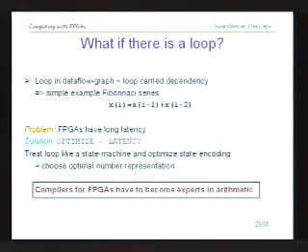The way to deal with that is, for example, to choose a number representation where this add can be done very quickly. So you could transform x and y into a redundant representation and use redundant arithmetic to speed up the actual computation. With this trick, you can try to make up for the 5 times slower adder that you have in an FPGA as compared to a microprocessor.